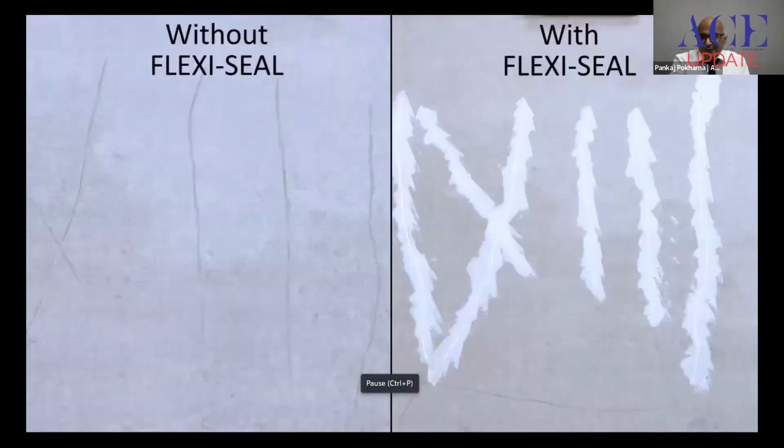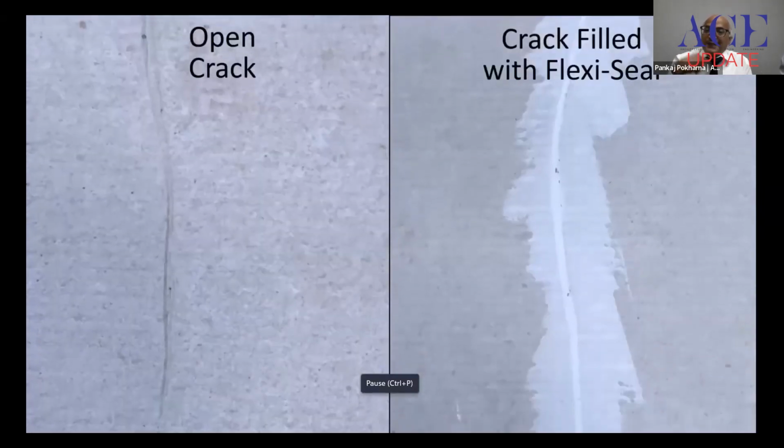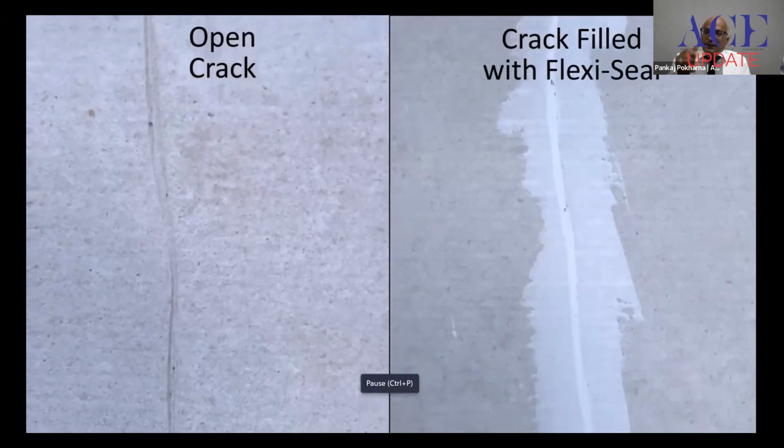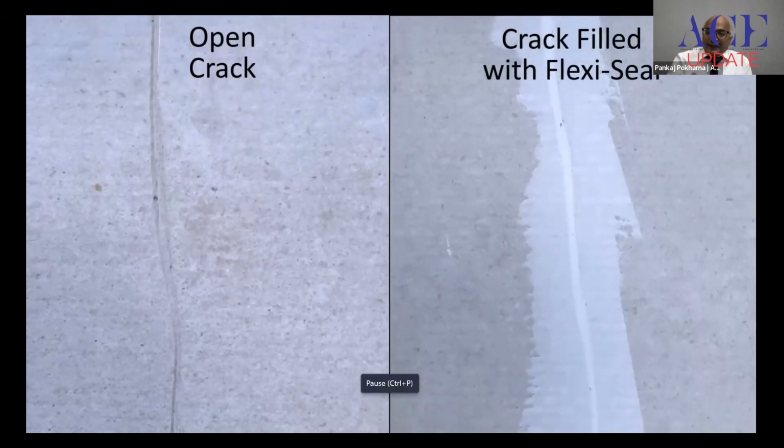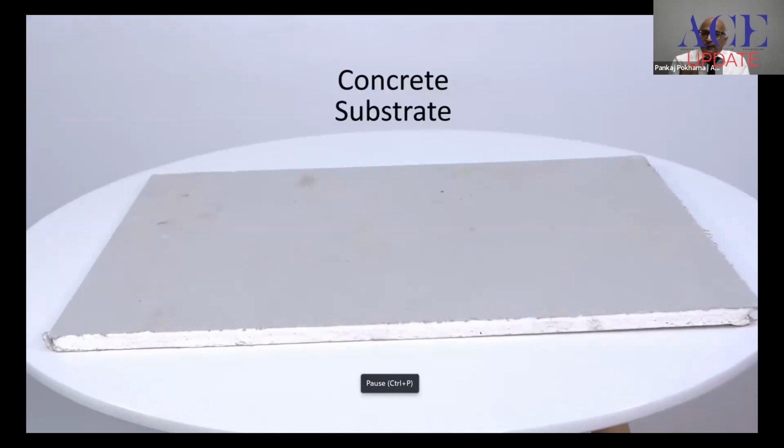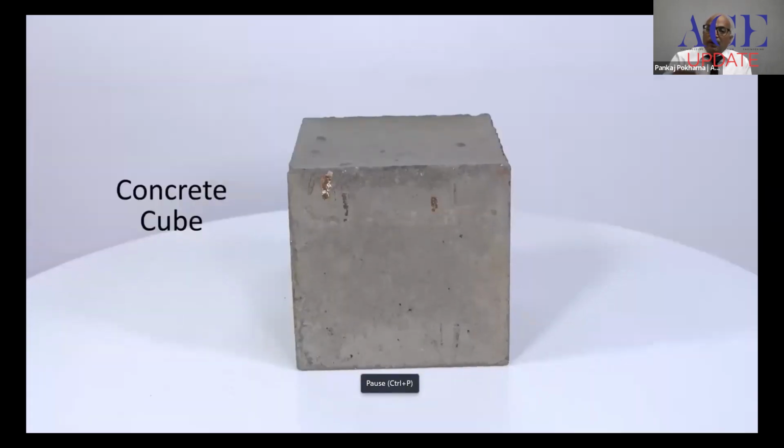So now you see all these cracks are filled. Sometimes when there are bigger cracks and deeper cracks, this filling requires a second time also, because by its weight, it will sag inside the crack. A big crack will take more inside. So it has to be recoated after 24 hours.